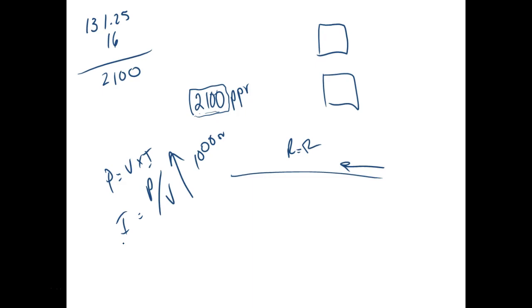You think about Alabama Power trying to send 750,000 watts at 240 volts. The wires would be bigger than I can stretch, right? You understand? So when they step it up so high, it gives them the ability to use a smaller gauge wire, and also instead of using copper, they can use aluminum, which makes it cheaper. Yeah, so it makes getting the power down here a lot cheaper.